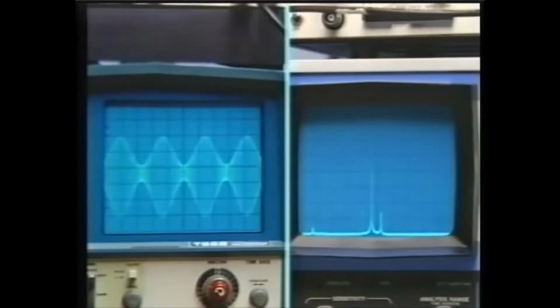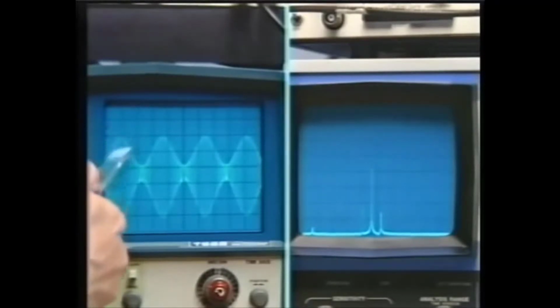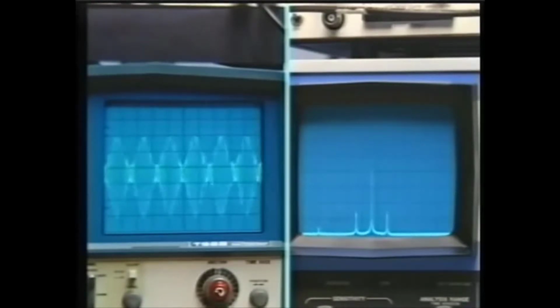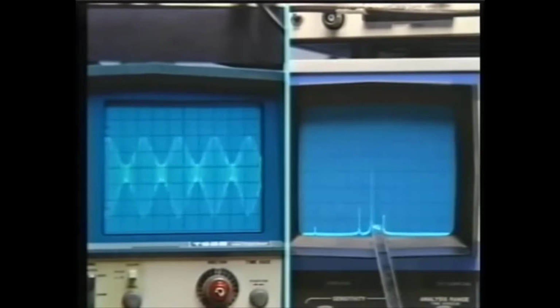Going back to the simplest, the sinusoidal carrier, another thing we can do is to vary the frequency of the sinusoidal signal that's modulating it. I'll make it higher, and you'll notice that the sidebands wander away from the carrier signal in the spectrum. The carrier signal doesn't have a frequency that's changing as I do this. It's just the width of the band due to the modulating signal. So this is the carrier, and these are the sidebands. That's right. And as we go out very far, those sidebands get gobbled up by the carrier itself. I'll come back to a nice, reasonable point there.